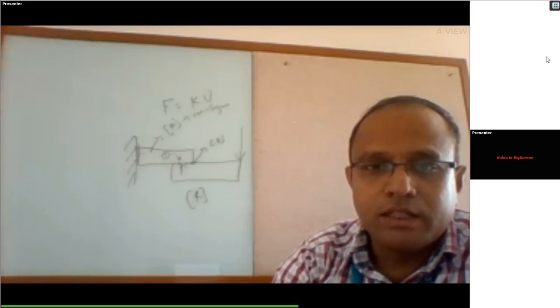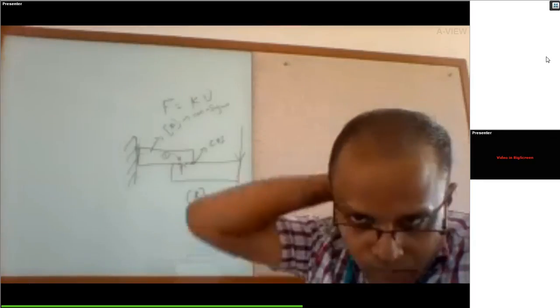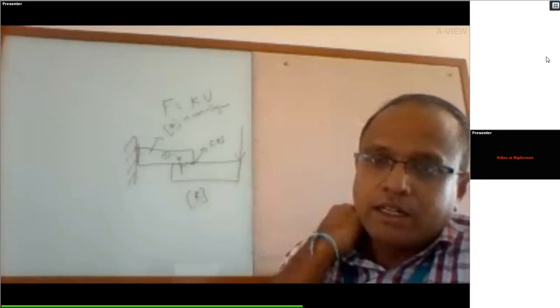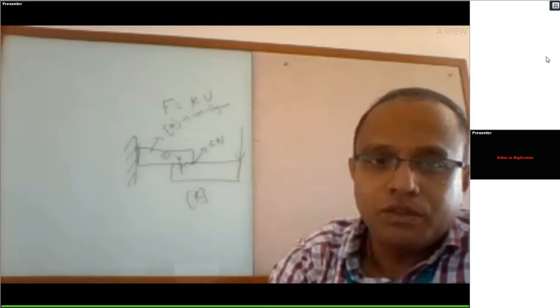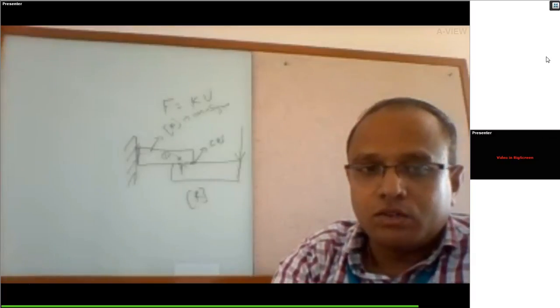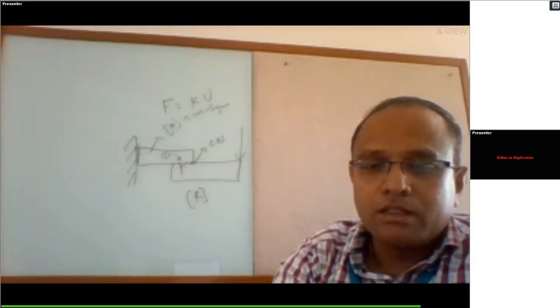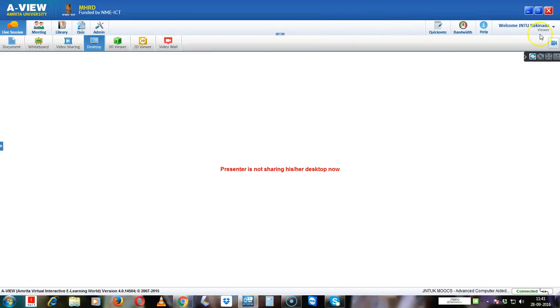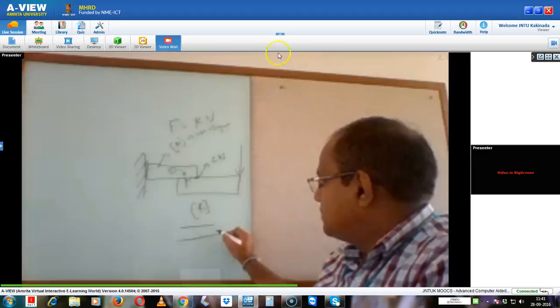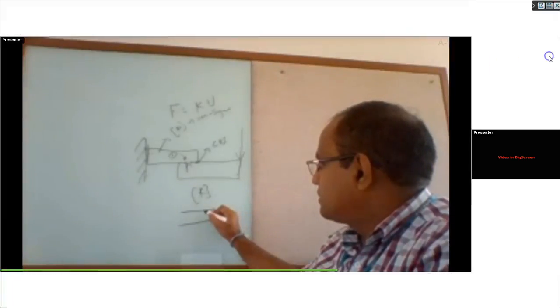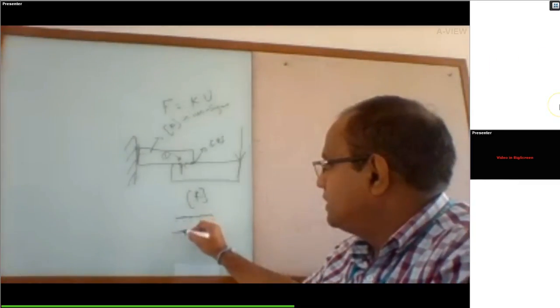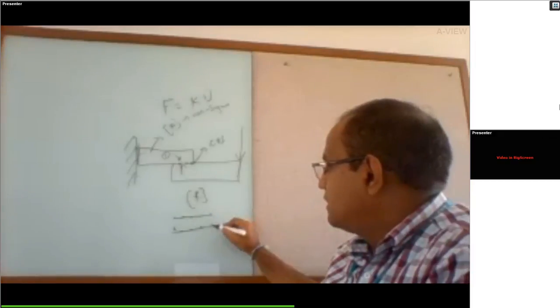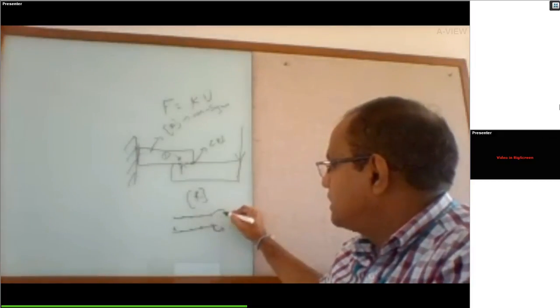In constraint equations, generally we establish relations between the degrees of freedom of the nodes. In couplings, we ensure that if you establish a relation between these nodes using CC, the deflection here and the deflection here will be the same.